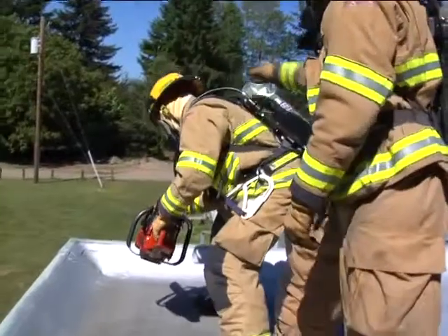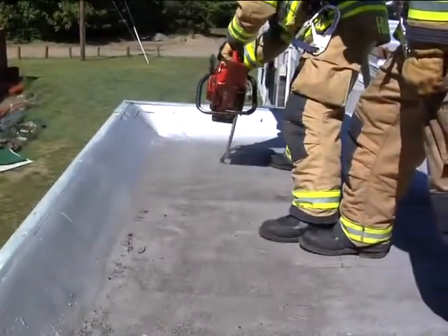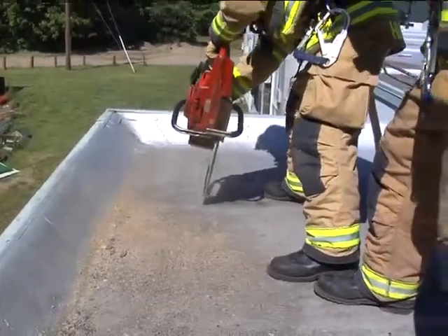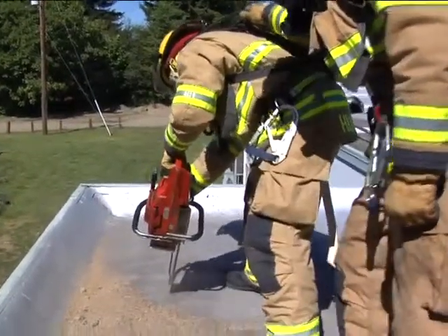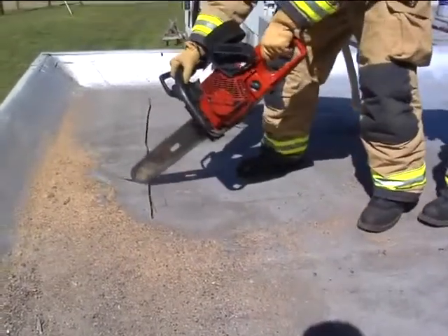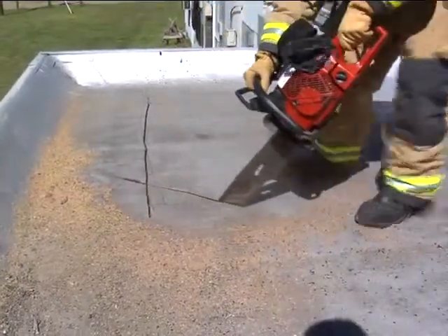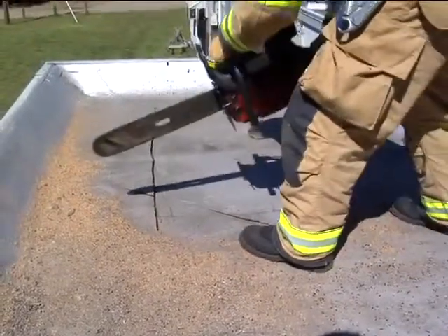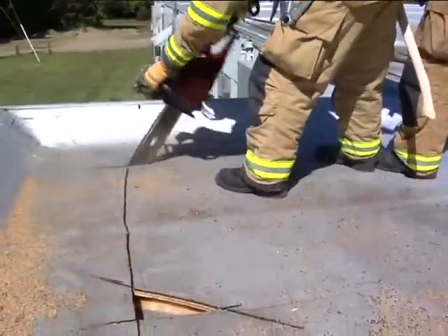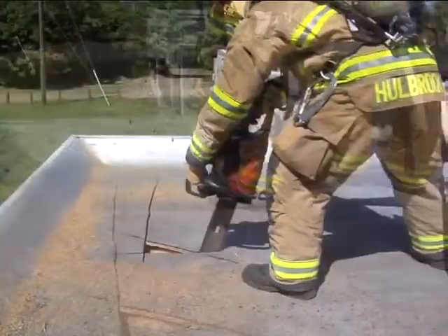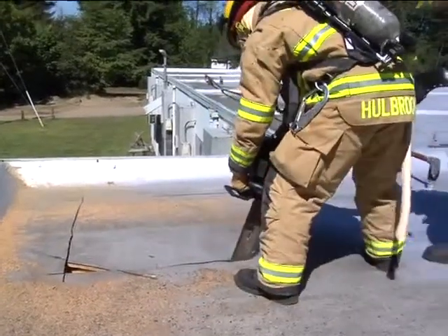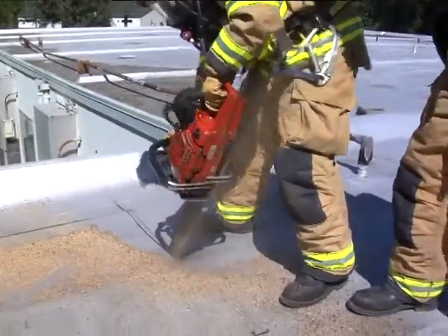Another firefighter secures the cutter's position from behind to ensure that he doesn't fall while using the cutting tool. Be sure that everyone stays clear of any moving parts of the chainsaw or rotary saw. Run the saw at full throttle while it is in contact with the roof decking to reduce the chance of binding. Make the first cut parallel to the roof support, then a triangular cut at the corner closest to you. Make 2 cuts perpendicular to the joist, being careful not to cut the joist. Then make the final cut parallel to the joist.